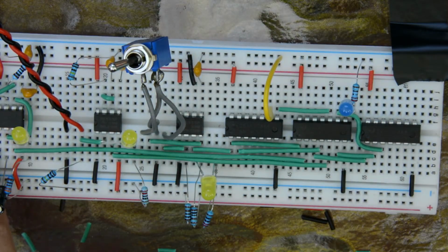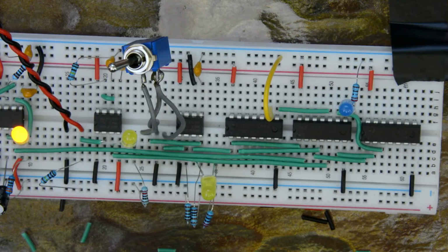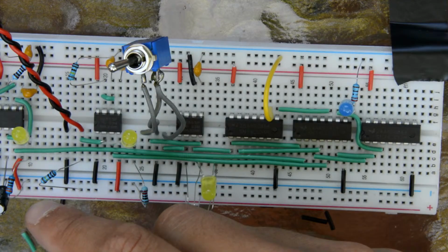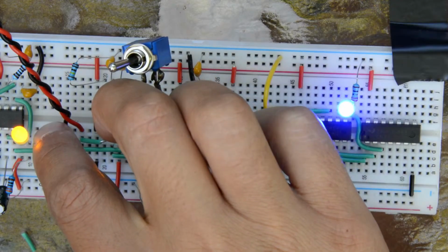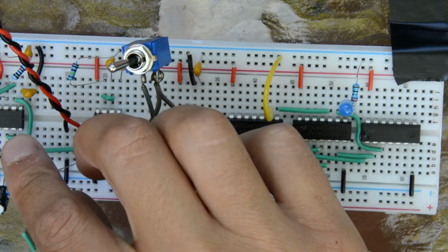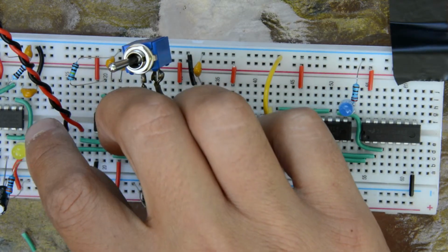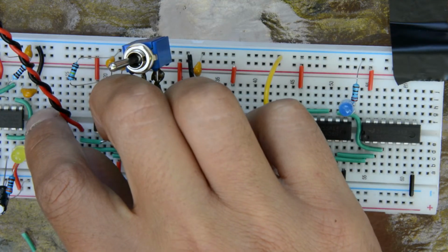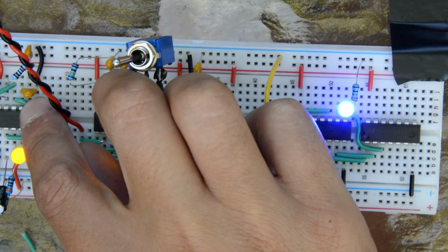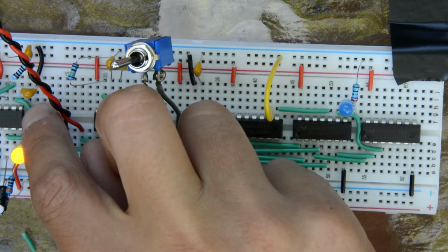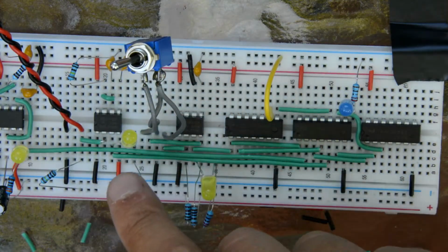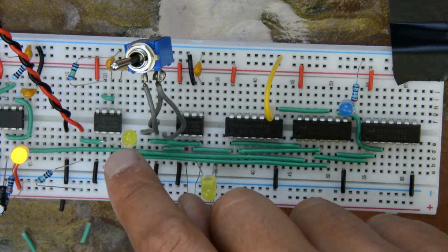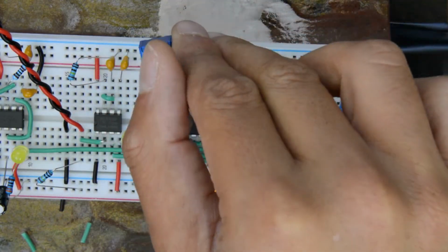Now the way that this astable configuration of the 555 works is that the 2 comparators inside of the 555 are used in a way that when a capacitor fills and discharges, it reaches the threshold in the resistor divider network, the voltage divider network inside here. It's kind of a complicated way to say it, but it's actually simple if you look at a block diagram of the 555 on Wikipedia. Okay, but then this other configuration is actually really simple.